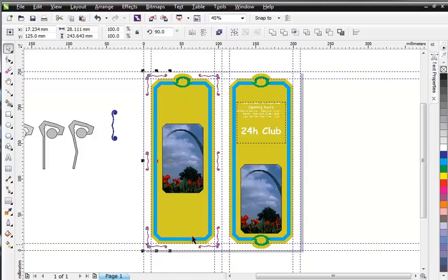Select the figures on the left, hold Shift and select the figures on the right. Let's now group them. This way all the figures will react as one element. Go to Arrange menu and click on Group. Duplicate this group and move it to the side.